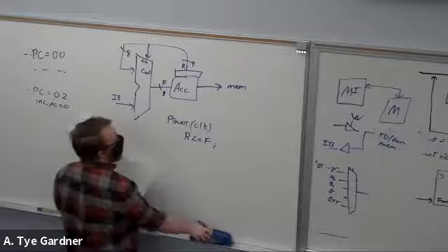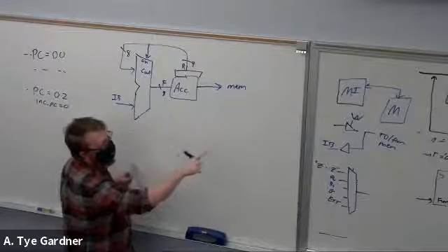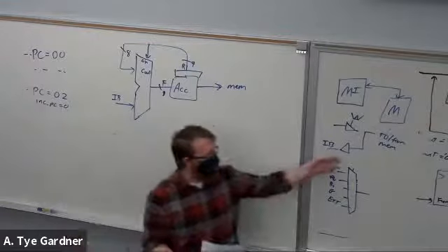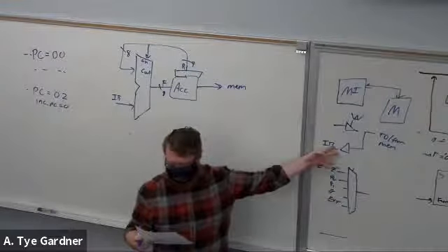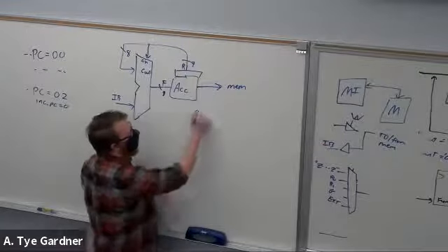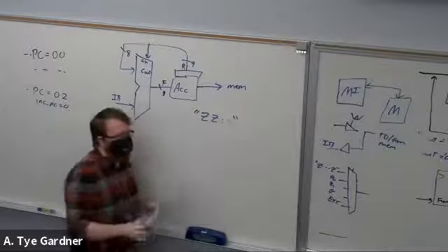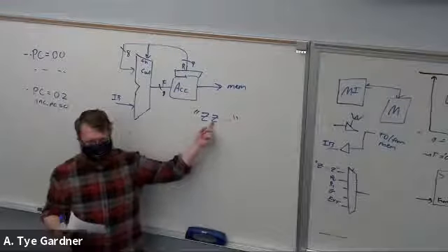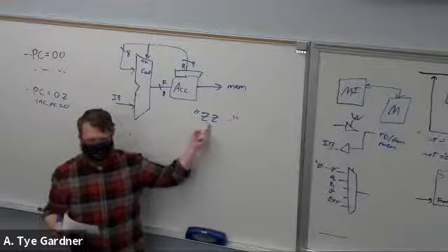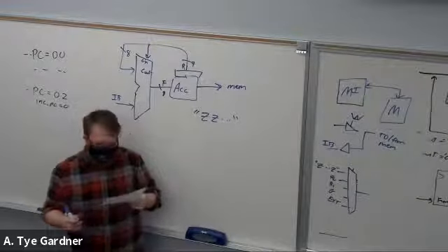The output register was the next part of project 2, right? Which I drew up there. I already did that one, which is just the when-else statement on this driver. This is actually one of the weird things I will point out. When you write Z's, you need the right number of Z's for however big your bus is, so 8 or 9. And they have to be capital. It doesn't like lowercase z's. This is one case where capitalization matters. It's kind of a weird thing.